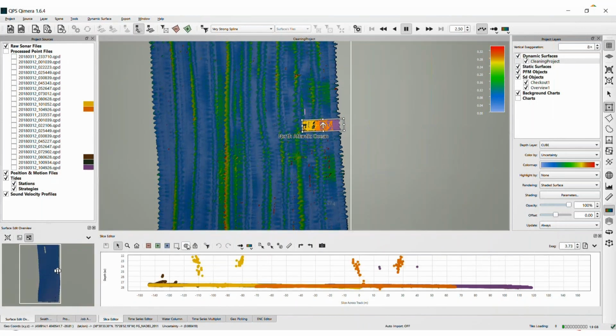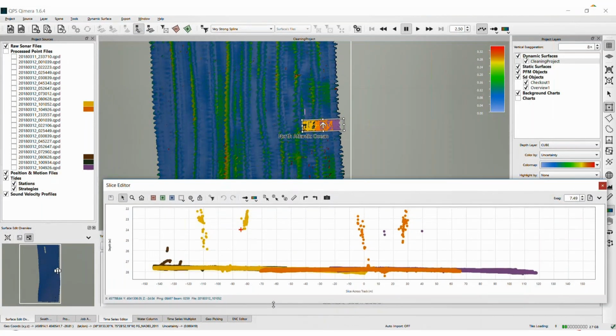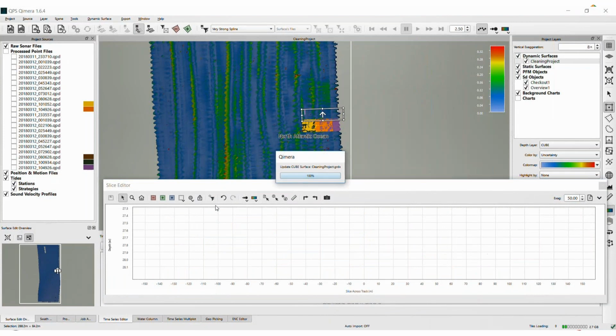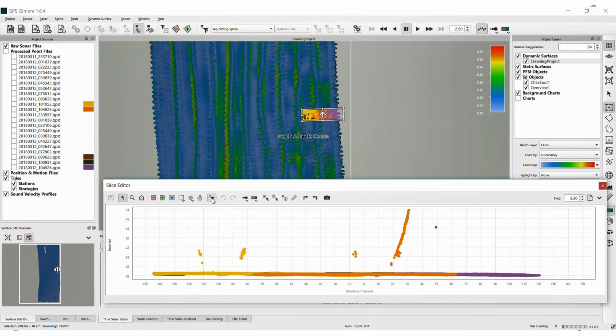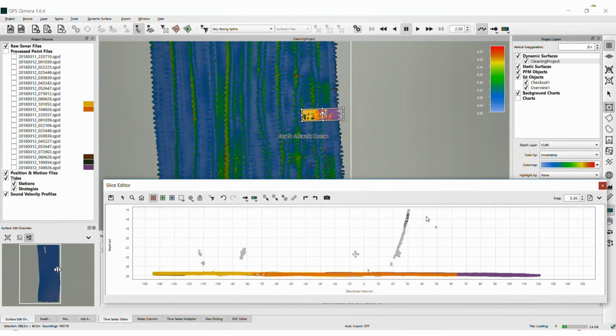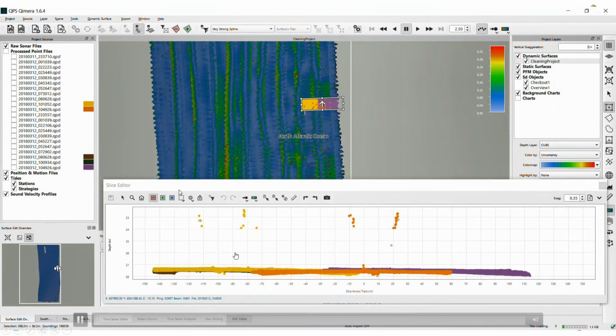Some side lobes there. And so in the meantime, that master project, they can still be doing the processing that's necessary. And then these edits are just going to come in with a simple flag to either reject or keep the soundings. So that's how it works. These things are happening simultaneously. So it's a very efficient workflow. You see there's some refraction in this data too. So I'm using Control-R to see the rejected soundings. And then I'm just going to move along here, do a little more slice editing with the filter.